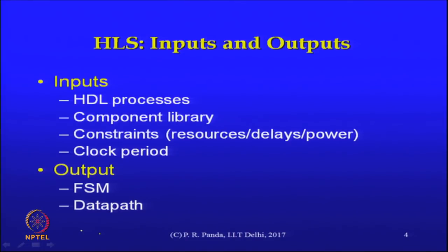At this level of abstraction, the output is not that final gate level netlist that we talked about. Remember, that is a lower level of abstraction, but here there would be a data path, what it looks like we will get to soon, and there would be a controller. At least these two components are there in the output of the behavioral synthesis.